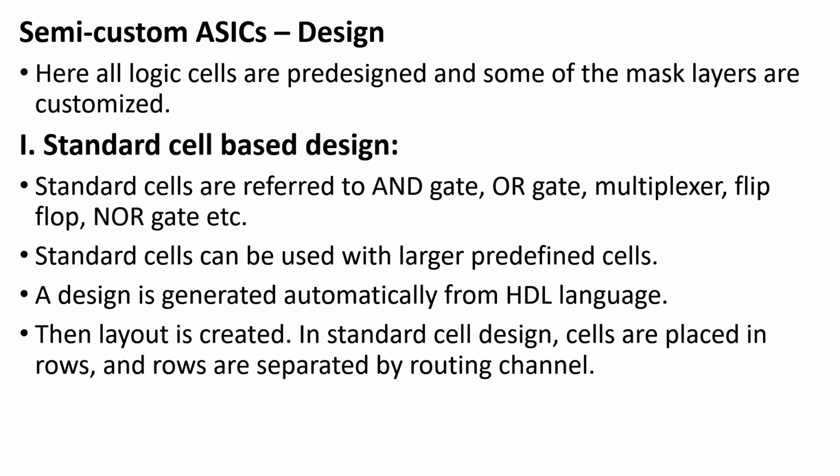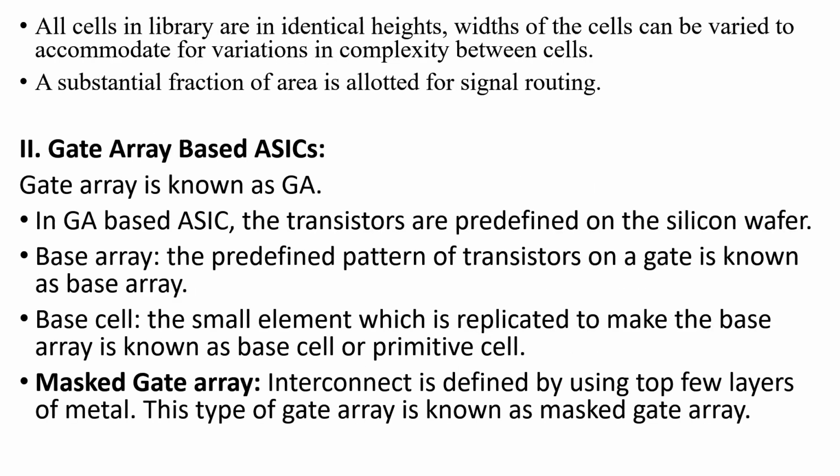In standard cell design, the cells are placed in rows and the rows are separated by using routing channels. All cells in the library are of identical height, whereas the widths of the cells can be varied to accommodate variations in the complexity between the cells. A substantial fraction of area is allotted for signal routing.